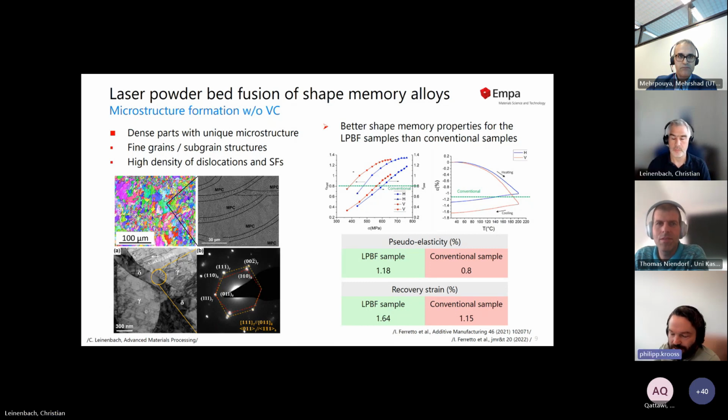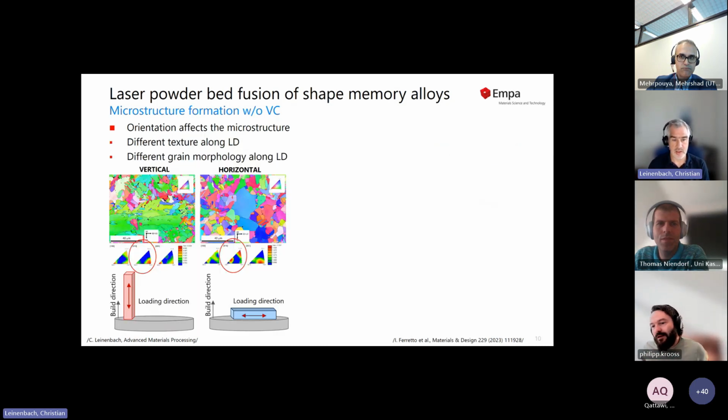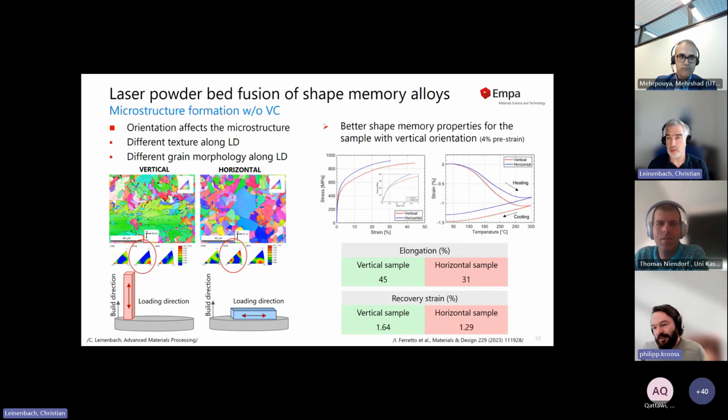I see. I was asking because we have different other alloy systems, which I will just briefly present, and there we also observed that the finer grain structure is not always bad for anisotropic shape memory alloys. So sometimes it helps. No, as I say here, it depends on what you do. We have these textures, and we do see differences in the properties already here. So that is actually the first level of microstructure control or property manipulation, if you want to say so. But this comes automatically out of the process. It's wonderful. Thank you. Good.